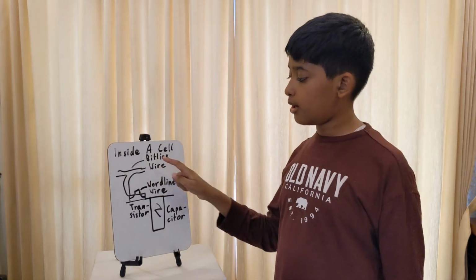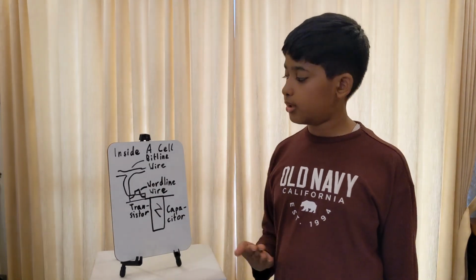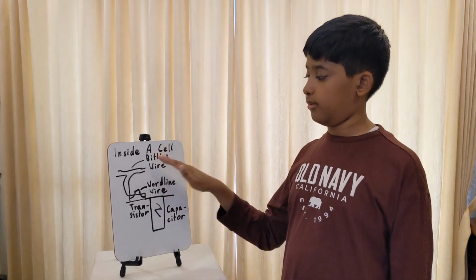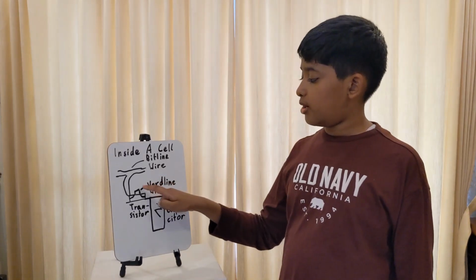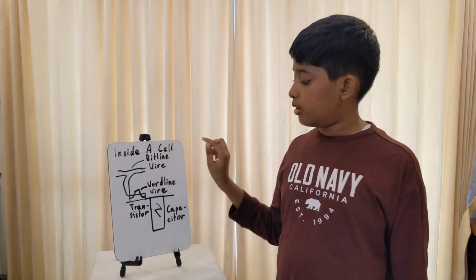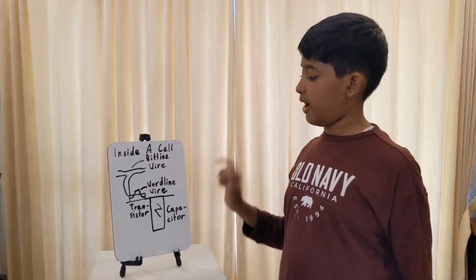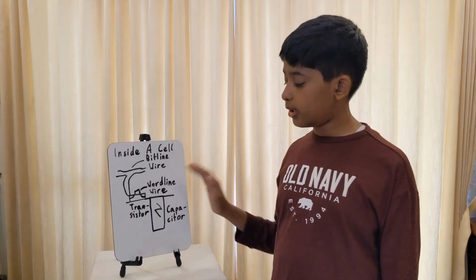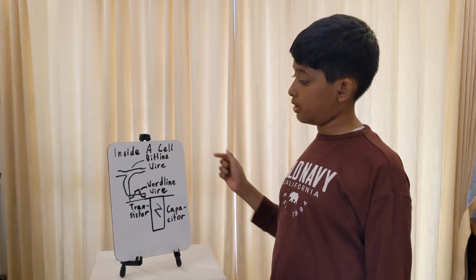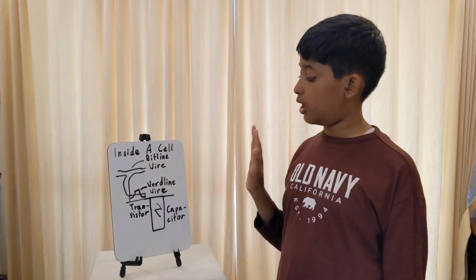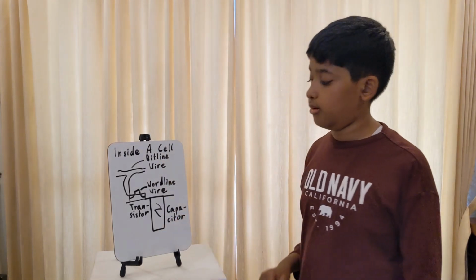The actual wire that we use for reading and writing data is the bitline wire. In the grid, this goes vertically. When the wordline wire is turned on, the bitline wire connects to the capacitor, and whatever charge is in the capacitor goes through the bitline wire. Then, whatever is in the bitline wire can either charge or discharge the capacitor.